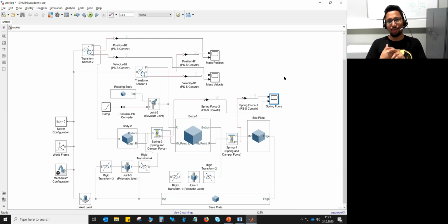If you have a body which is vibrating, whose mass and stiffness coefficient is too much, and it oscillates with a very high amplitude, in order to dampen that, they just add another mass whose mass is much less than the initial one, and the spring coefficient is also less than the initial one, and then it dampens out.